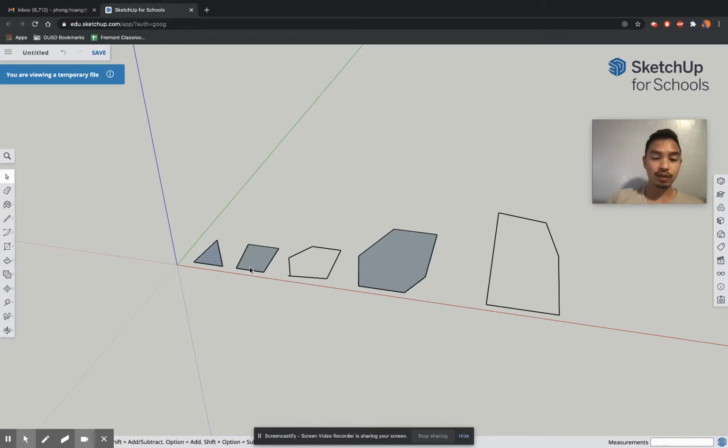All right. The other thing to recognize is how you create this 3D object. Once you have yourself a surface, you are able to use the Push/Pull tool. It is this guy here. Or you can just press P on the keyboard and the Push/Pull icon will come up. The way you do that is you hover over a surface, and it will highlight with tiny little blue dots. That means that the surface is ready to be extruded, meaning it's going to be able to be pushed and pulled into 3-dimensional space.